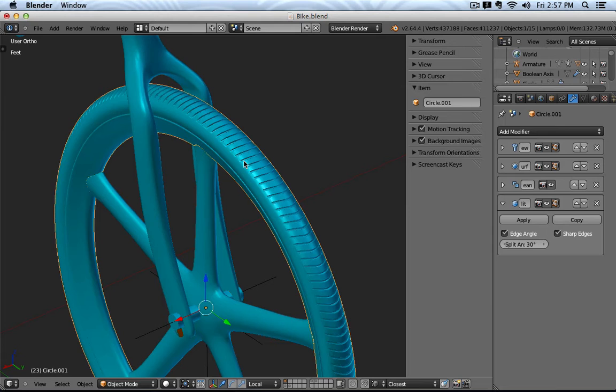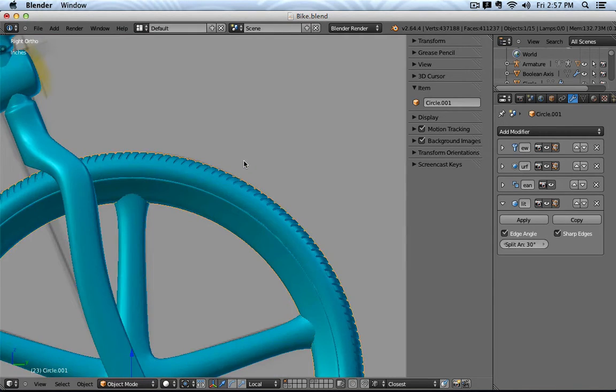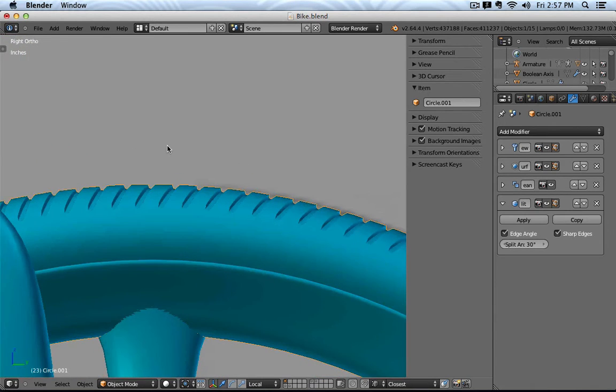It's more like a visual helper for us how a shape could look like. So even when we do, technically speaking, sketch modeling or concept modeling, the basic input surfaces we can still make use of inside Alias and then touch up the missing features, for example, like the fillets here or the edge roundings up here if we want those.